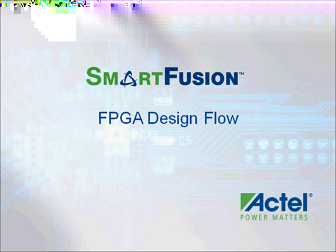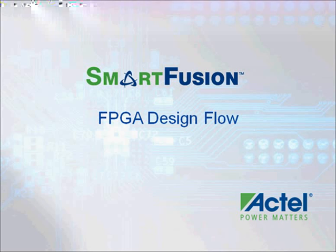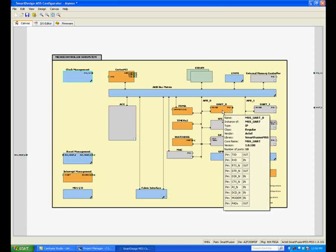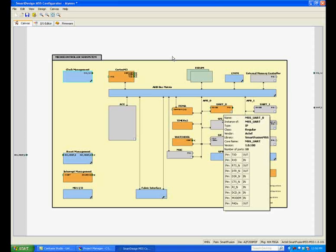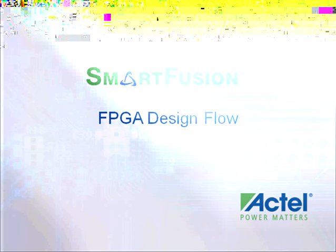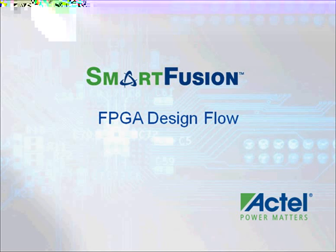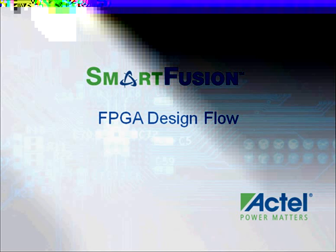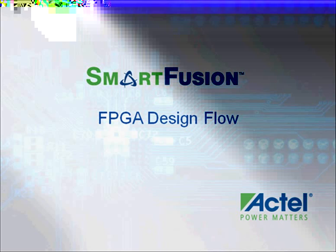This design also uses UART 0 in the MSS. Note that when selected, UART 0 already has predetermined connections to the top-level pins for the TXD and RXD ports. Click the SmartDesign MSS Configurator I/O Editor tab to see the pin numbers and I/O attributes. The configuration of the UART is performed on the software development side using SoftConsole or other software IDE tools.